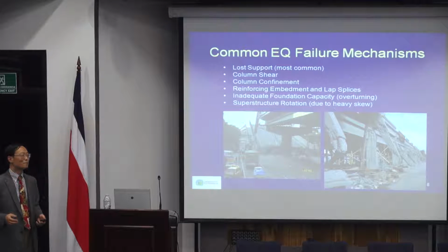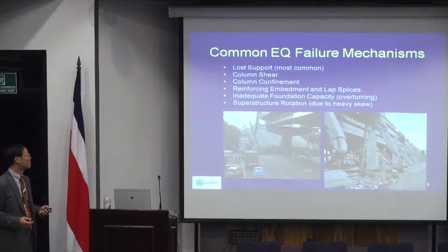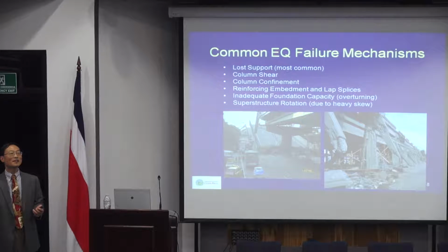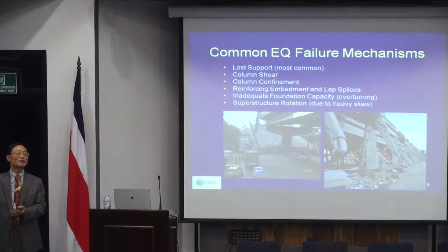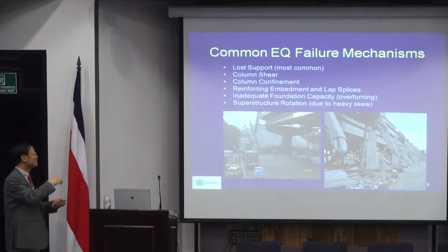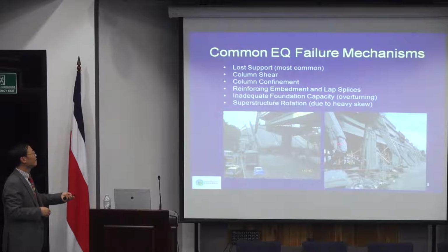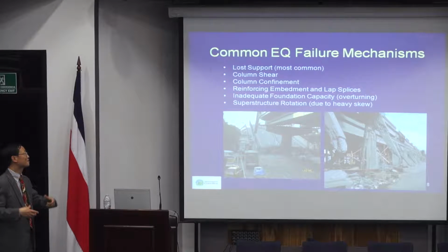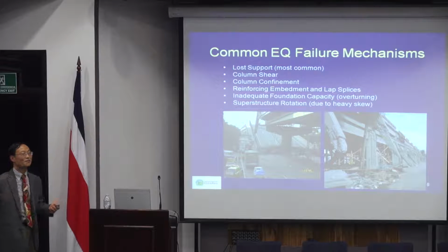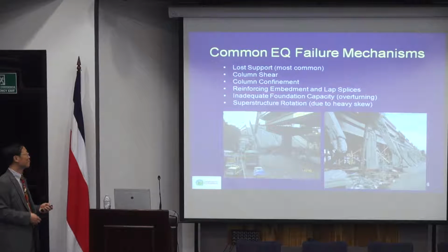Only when an earthquake comes and shakes, because the superstructure has a big mass, when that superstructure moves it introduces an inertial force that may shear off the column if the column is so small, because it was not designed for lateral shear load. That's another mode. The third mode is to look at that pier.